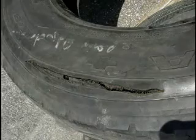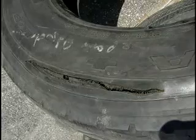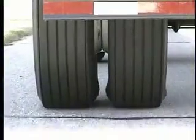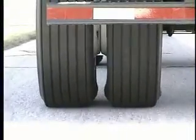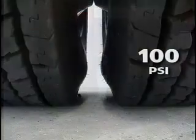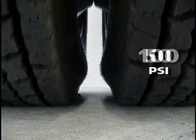A close look at the sidewall plies in a zipper rupture will reveal the uneven detachment of the cords within the sidewall, and the ends of the individual cables have a stretched appearance. Looking at the deflection of a flat tire on a loaded dual tire assembly will show how this condition is caused. Here is a view of both tires at 100 psi with normal deflection.